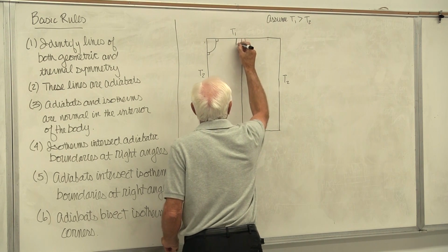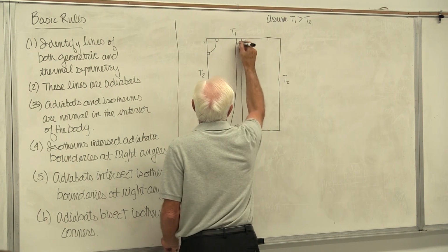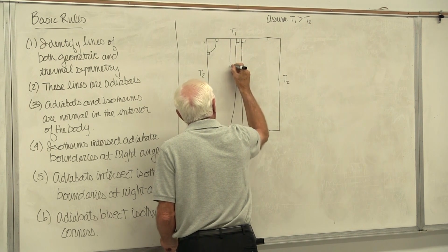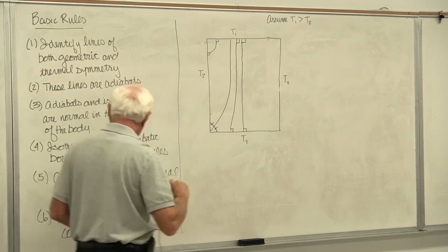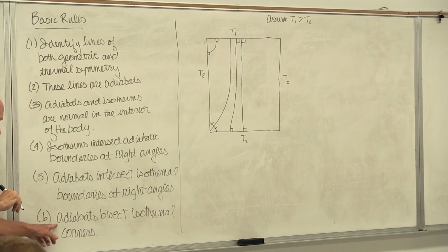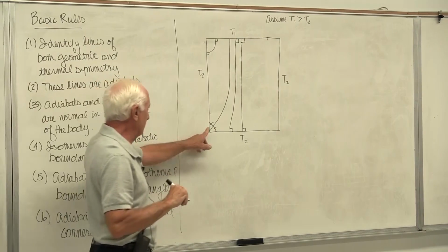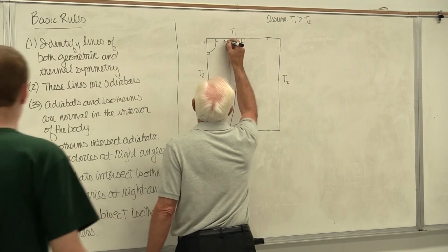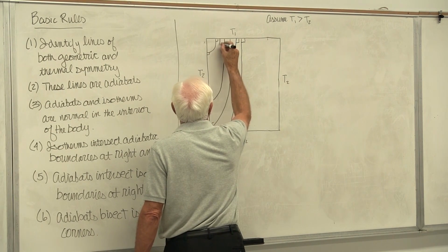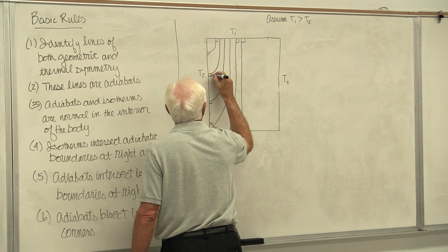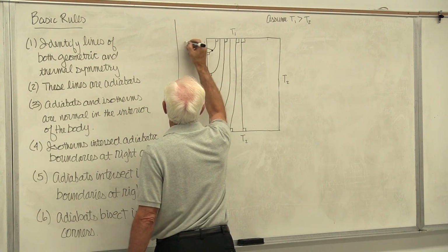Okay. Leaves here, comes down, goes out there. Leaves here, comes down. Maybe that one will bisect the corner. Rule 6. If a heat flow line goes into an isothermal, it bisects that angle. Okay, 90-degree angle, 45, 45. These guys are isotherms. I'm sorry, adiabats.